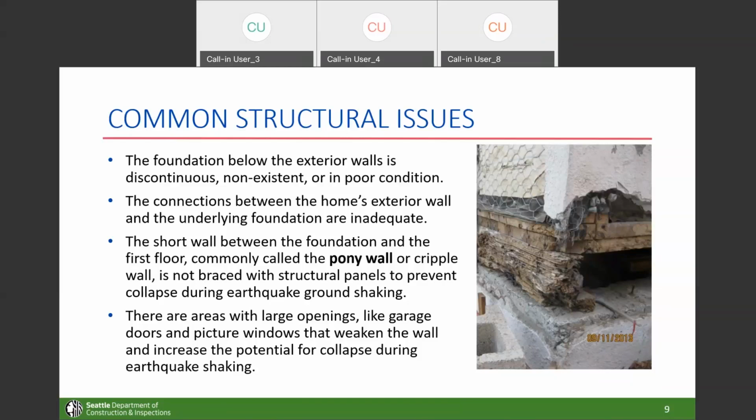Brick foundation, that's a tough one. Brick foundations are real unique animals, and if it is reinforced, it may be possible, but by the time it's determined to have adequate reinforcing, you've already involved a professional. Those are very interesting and often very robust foundations, but for the Project Impact drawings, it's light frame on a simple concrete foundation. Maybe this will answer another question: if you have a cinder block or concrete masonry unit foundation, sometimes they would fill every other block, or fill the blocks and reinforce them sporadically.